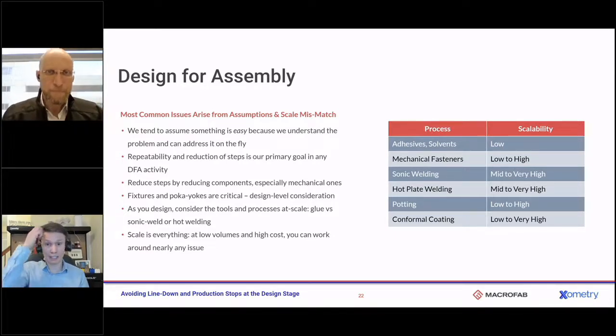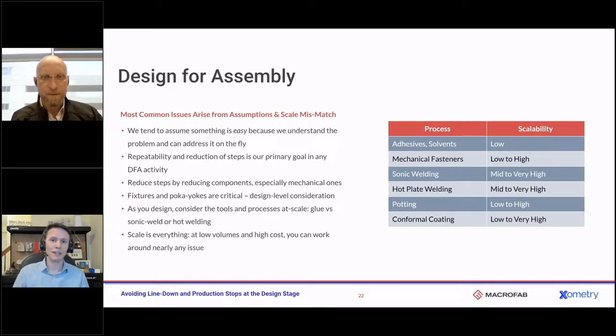Reducing fasteners: you usually see this if you're mounting your PCB with plastite screws, so like thread-forming screws in your plastic, which I love, by the way, I love plastite screws. But depending on volume, right? At first it's like, okay, cool, I have 4 screws, and that's it. But then multiply that by thousands, and you have a huge manual burden.